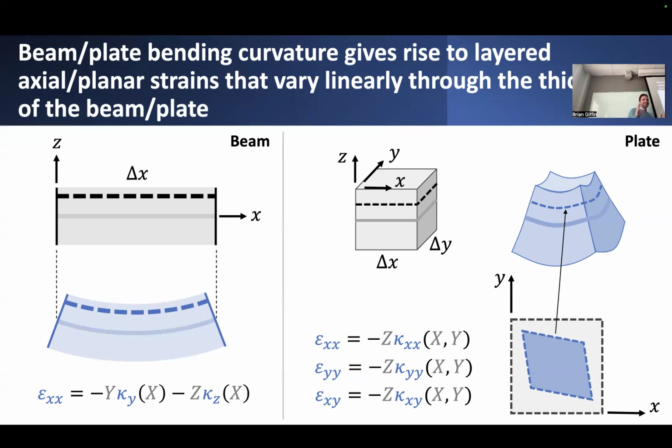That's fundamentally an assumption of beam theory as well, and it applies really only to straight beams. There are situations where if you had an initially curved beam and you tried to deform that beam, now some of those assumptions fly out the window. But if you have a perfectly straight beam to begin with, and if you assume relatively small bending deformations take place, then it's reasonable to assume that this neutral axis maintains its same length.